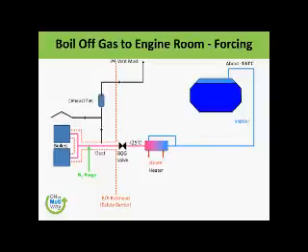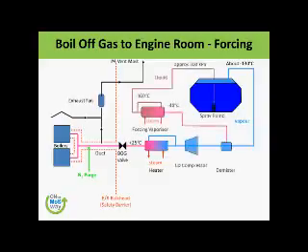And then of course we have the whole system where, if we do not have the liquid vapor coming to us, we will start the spray pump, about 300 kPa liquid at minus 161 degrees. We give it to the vaporizer and heat it to a certain temperature, and then anything above minus 160 will automatically turn to vapor or gas.